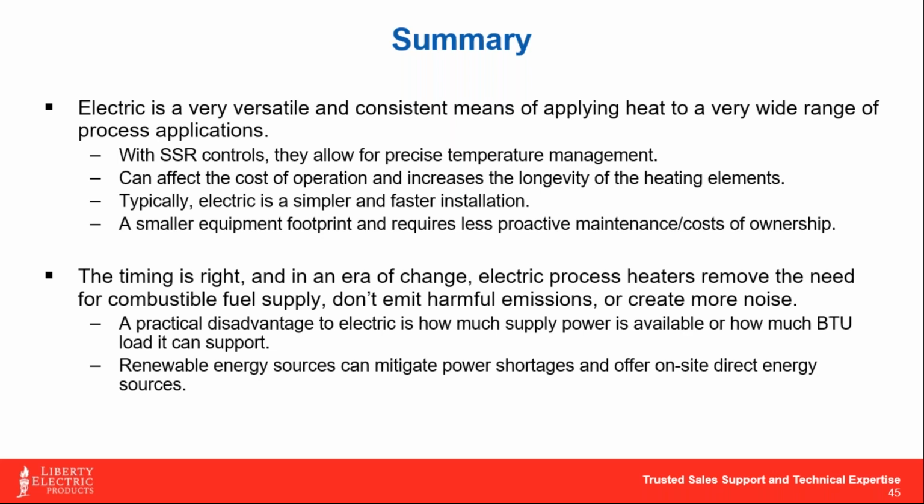Solid state relay controls, which I told you before I'm a big fan of, give you very precise temperature management, and they also help the longevity of your investment. If you're going to invest or spend $20,000 on a process circulation heater, you'd like to have this thing around in 20 years. So the SCR more than pays for itself in the long run.